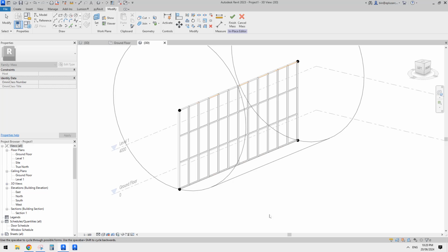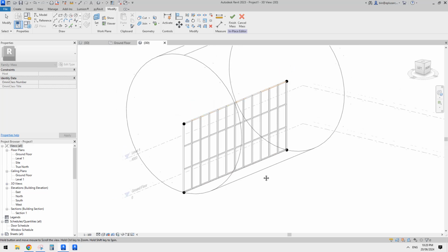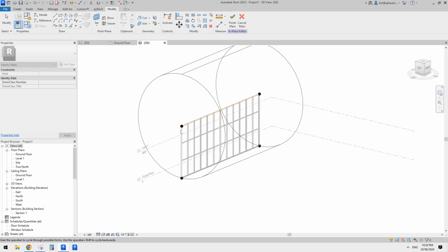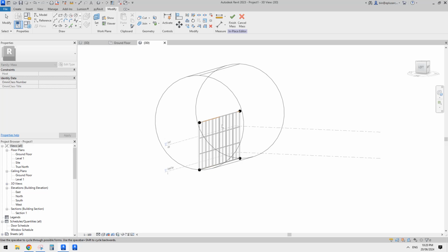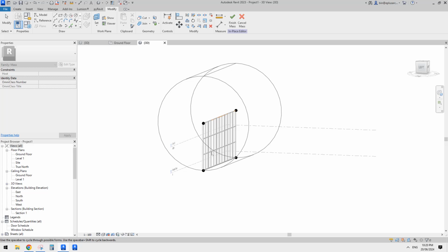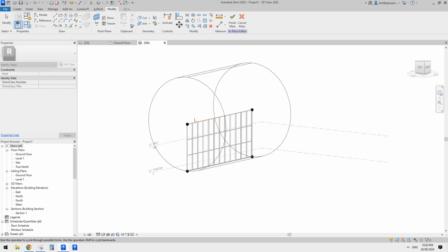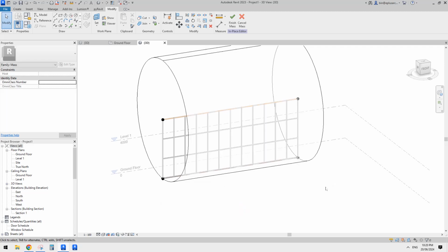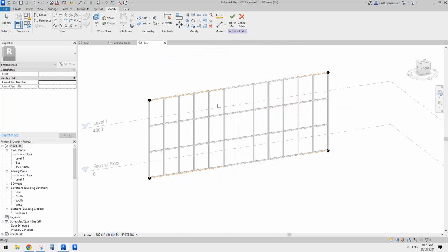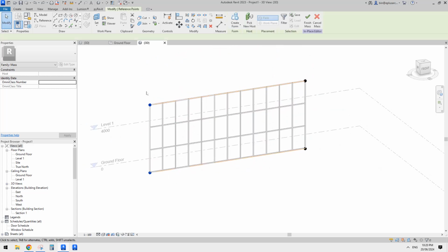Yeah, it's not on my other screen, so this is tricky, because usually if you use two parallel reference lines, you will have three different options. One is a revolve, using this as an axis line and this as a profile, and the other way around, and then also an extrusion or sweep, just connecting them. In this case, because the option is not on my screen, I can't really find it. So if I click anywhere, it'll create this revolve thing, which is not what I want. So I'm going to just close it.